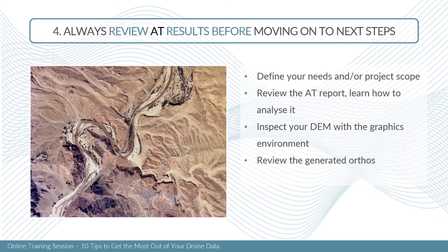The same way goes for the ortho. When you have generated the ortho, you can review them in the graphics environment. Just a quick check to see everything is fine. And with the mosaic, you're gonna pan into your mosaic to see that all the color balance and the seam lines, everything is good. You have a good color balance, seamless mosaic. So you're looking to find out if there is any issue in your mosaic.